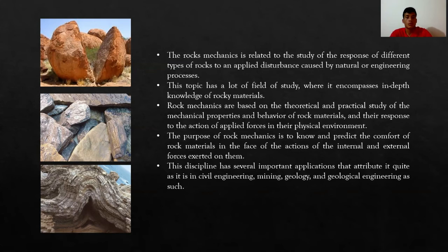The purpose of rock mechanics is to know and treat the behavior of rock materials in the face of the action of the internal and external forces exerted on them. The different areas of application of rock mechanics are grouped into: One, when the rock material constitutes the structure, such as tunnel excavation and slopes. Two, when the rock is the support of the structures, such as foundations of buildings and dams. Three, when rocks are used as building materials, such as embankments, gabions, and fillings.